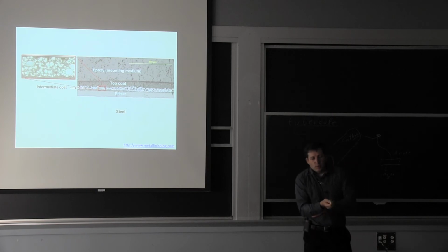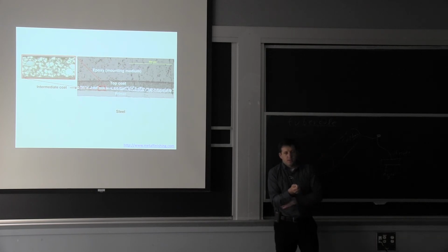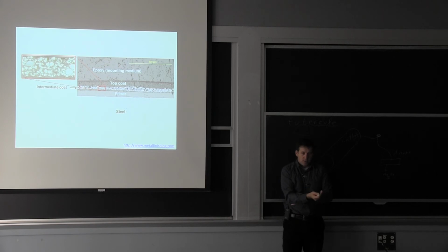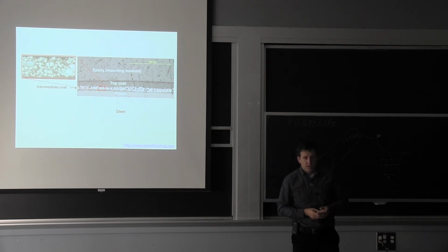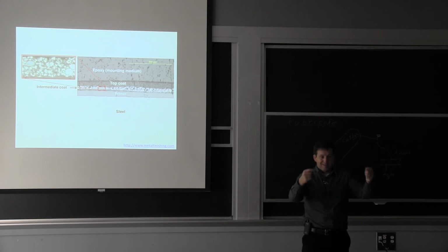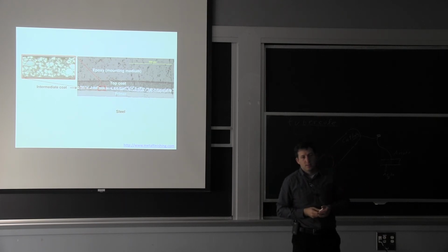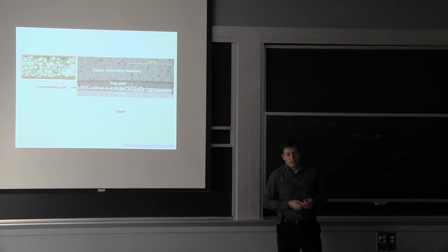The primer is mostly there as a bond, because your surface always has moisture, so you need to wet that surface and capture that moisture so it actually absorbs anything that's existing. That's really its main function. And then that material will adhere better with your hard coating that you put on the outside, that's there as a barrier so nothing else comes back in. Yes? How do you put it on? Do you paint it or spray it?